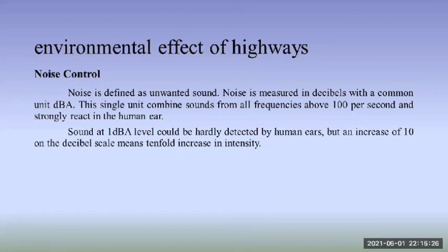In a quiet residential area at night, the ambient noise is measured from 32 to 43 decibels. The urban residential district at daytime limit is about 41 to 53 decibels, and in industrial areas, the range is 48 to 66 decibels. And in downtown commercial areas with heavy traffic, it is 62 to 73 decibels.